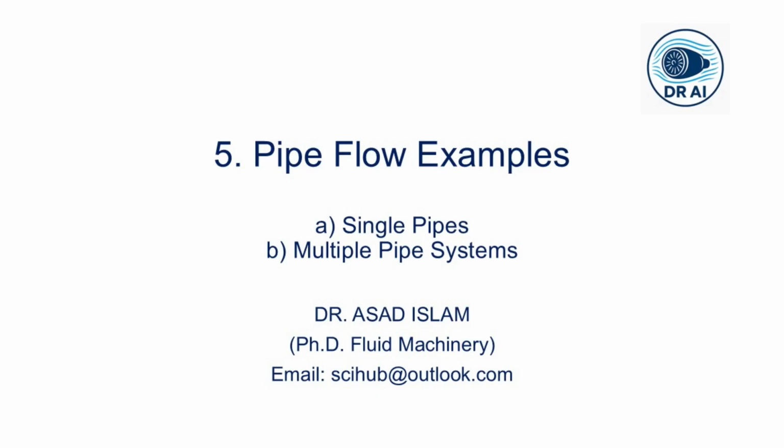Over the last several lectures, we have been building a toolkit. It's been quite a journey. We started with the fundamentals of pipe flow, understanding laminar and turbulent regimes. We derived exact solutions for laminar flow, giving us Poiseuille's law and f equals 64 over Reynolds number relationship. Then we tackled the complex world of turbulent flow, learning about the Reynolds stresses and the viscous sublayer.